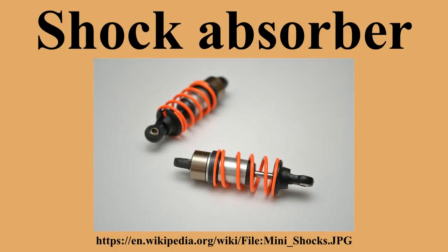Acceleration-sensitive damping. The next phase in shock absorber evolution was the development of a shock absorber that could sense and respond not just to situational changes from bumpy to smooth, but to individual bumps in the road in a near-instantaneous reaction. This was achieved through a change in the design of the compression valve, and has been termed acceleration-sensitive damping, or ASD.